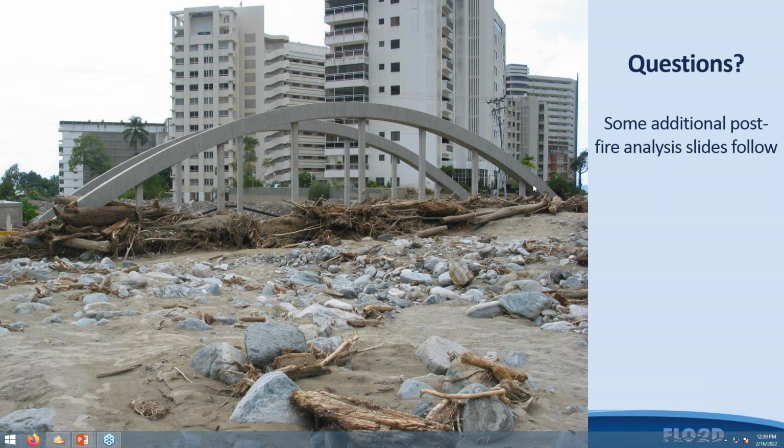Now, if you want to compute a comparable erosion of the channel, you would have to use one of the sediment transport equations, and that gets into the concept of two-phase flow, which we're going to cover next time. So in terms of predicting the scour of the channel along with a mudflow event, we'll cover that next week. It's a little bit complicated. In general, for the mudflow portion of the model, the model will predict flow cessation and flow remobilization. For the sediment transport portion of the model, you'll predict scour and erosion.